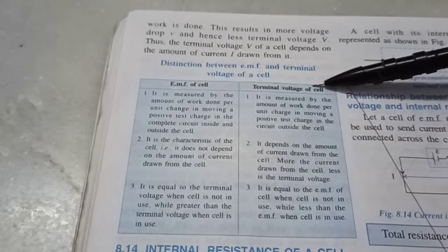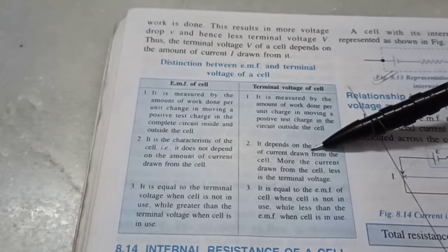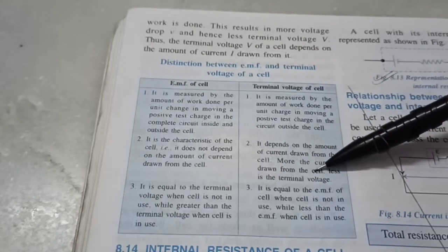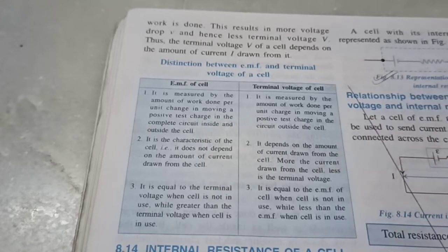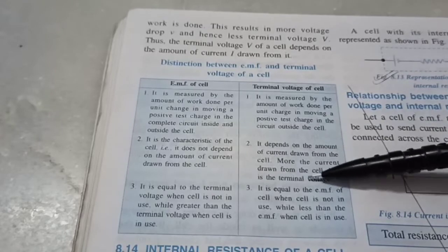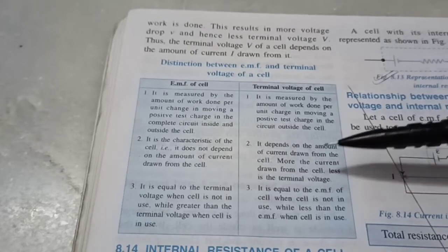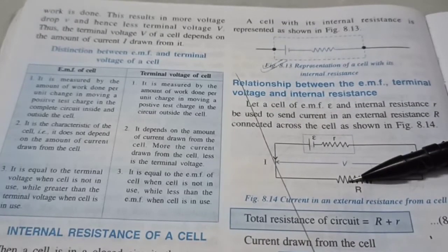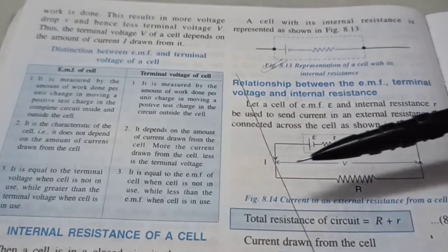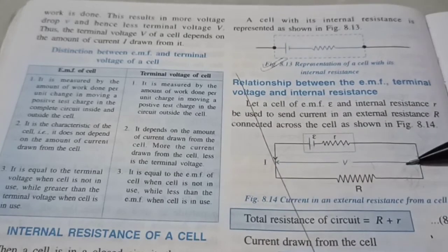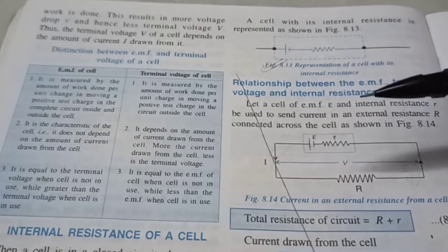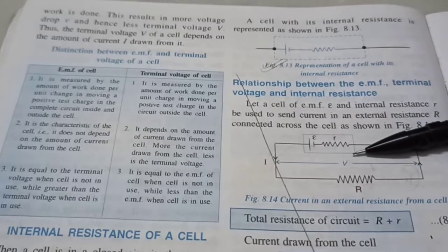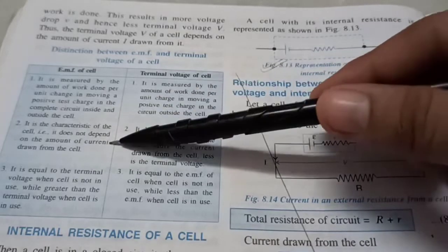The terminal voltage of the cell, however, depends on the amount of current being drawn. If you use an appliance which is using a lot of current, then there will be a lot of voltage drop as well. So the terminal voltage will become less. So if this device was using a lot of current, then perhaps the voltage drop won't be just 0.2 volt, it would be 0.5 volt. So now the potential difference across its ends is 5.5 volt, not 5.8. So the voltage drop depends upon the amount of current being withdrawn, and so does the potential difference. Whereas EMF doesn't depend on that.